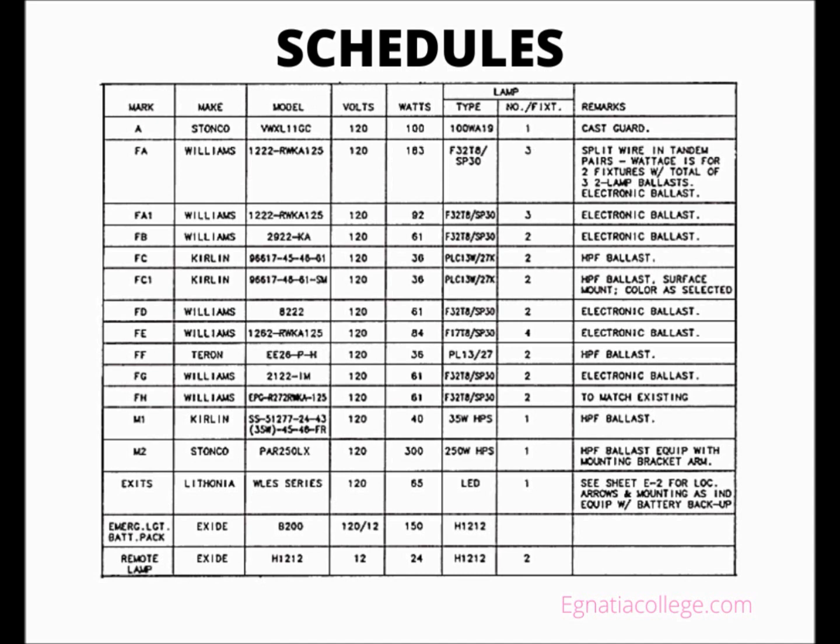The School Edition Fixture Schedule A9. Floor Plans E7 and E14 on drawing E1 show type FA light fixture to be the light source for the classrooms. The remarks column indicates some special wiring and specific ballast type requirements. The first and second floor reflected ceiling plans E15 and E16 on drawing E7 indicate light fixture type FA to be a 2 foot by 4 foot light fixture mounted end to end.